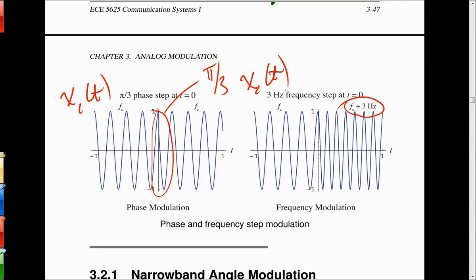So Sean's question about where is the modulation: notice it's constant envelope. You don't see any fluctuations in the carrier itself. It just holds steady and constant. And that's desirable. Actually, if you were really thinking hard about the future, you'd say, oh, we've got modulation contained in the frequency or the phase. What happens if we start fluctuating the amplitude around? You can actually do a combination of the two if you want to.